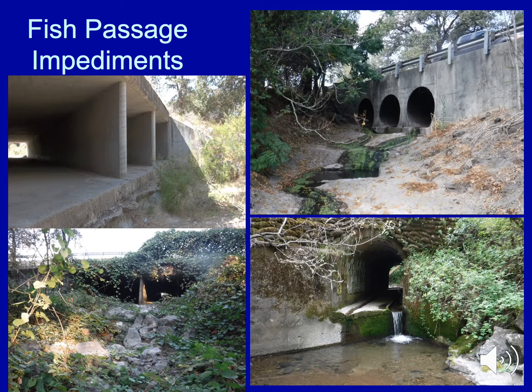All of these, particularly White Chica here, have very inadequate jump pools to actually try to ascend into that culvert. Pretty classic scour of the downstream side of concrete aprons. You see a lot of that. The solution is often to install a bunch of riprap to prevent further scour and structure failure.